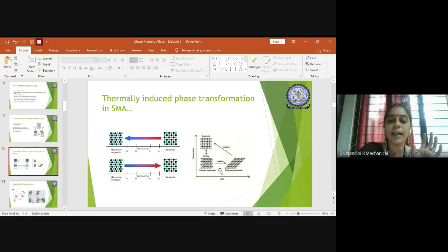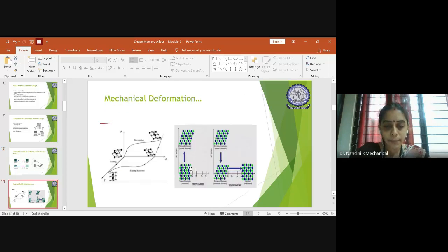So here one of the figures has to show the pure structure of the alloy, how it looked before loading. Once it is loaded, it is deformed. Before deformation, it will look similar to this. But since it is heated and cooled, it will be twinned martensite, right? Subjecting it to heating and cooling, you will call that a twinned martensite. But the structure will be almost similar to the initial position of the shape memory alloy. So this is just to make you understand the changes.